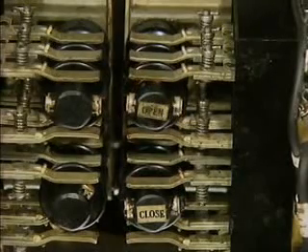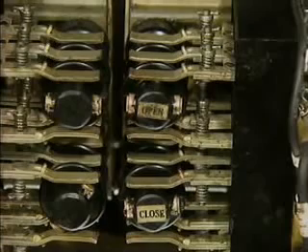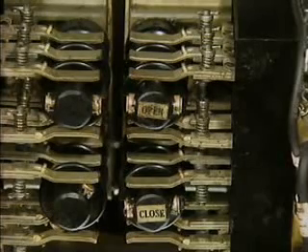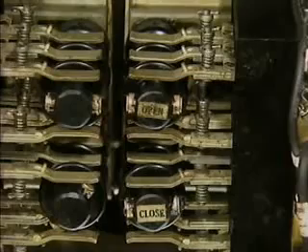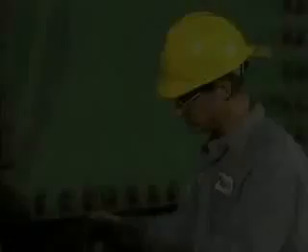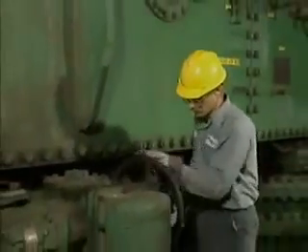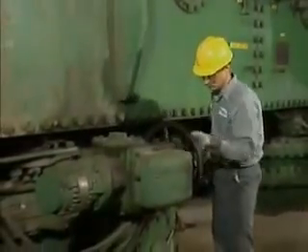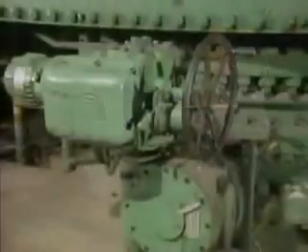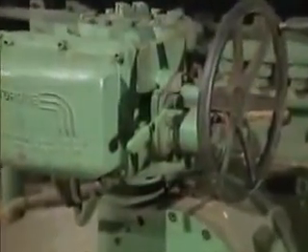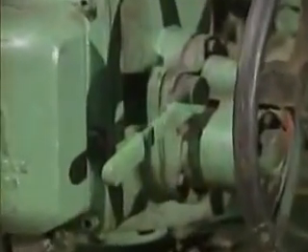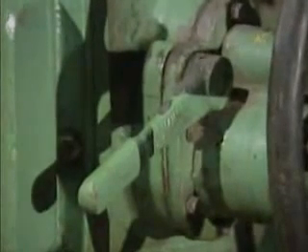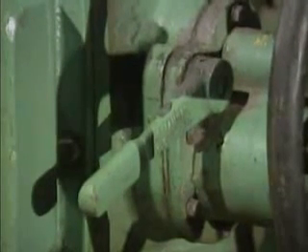A limit switch may be used to indicate the position of a valve and to ensure that power is stopped when the valve is in the fully open or the fully closed position. Some electric motor operators can be operated manually with a hand wheel if necessary. Typically, the motor operator has a lever that connects the hand wheel to the gears and at the same time disconnects the motor from the gears.